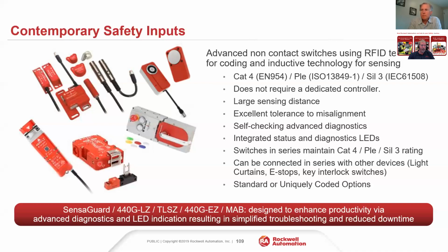The key here is that this RFID actuator is mounted separately from this key, because to reach the current safety standards to the highest level, you need to have key break detection. So this provides that key break detection. If this key is inside that switch and this actuator is not at the switch, we consider that a broken key and fault the switch.